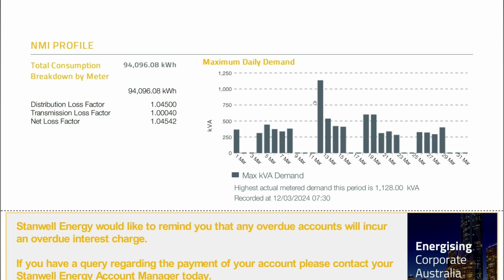So on the Tuesday, we started up and it would have been everything going, all the AHUs going hard, the chillers staging all the way up, pumps running hard, and bang, peak demand hit here because of that one day. And now we're paying this money for 12 months. Even if it doesn't happen again next month, it doesn't matter. You are now locked into that tariff, that rate, and you're paying this amount for 12 months.